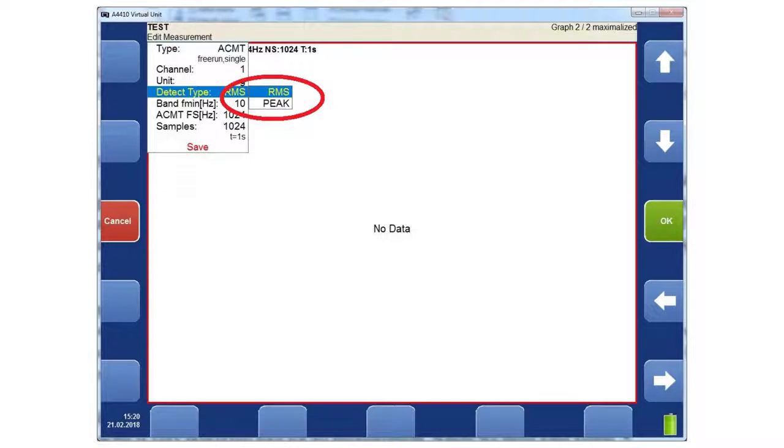It is clear when I select RMS compression, then the peaks in signal will be lower than peaks in original signal. It is the mathematic rule. The ACMT is a very powerful tool for all measurements where we need long signal, typically on slow speed machines, as I mentioned at the beginning.